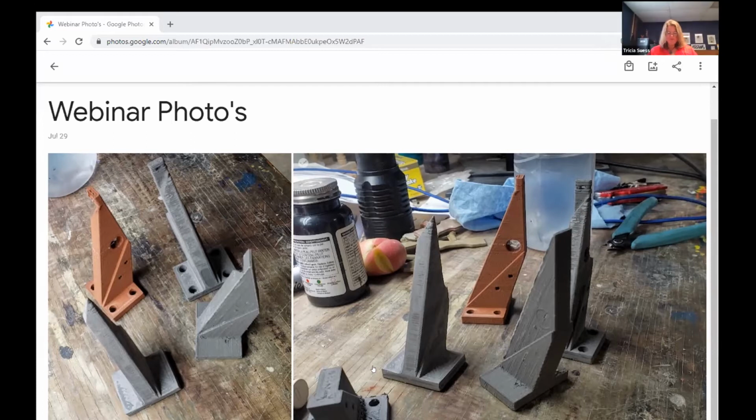So talk about infill for a minute. We get this question pretty frequently. What is the requirement for infill for parts that you're going to sinter? For me, I've always worked with 100% infill. Now, when you start to get to really large parts, that's where this webinar is really important. We're going to talk a little bit later about generative design and things like that.